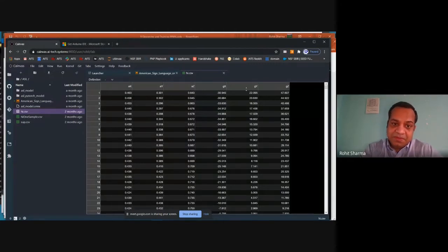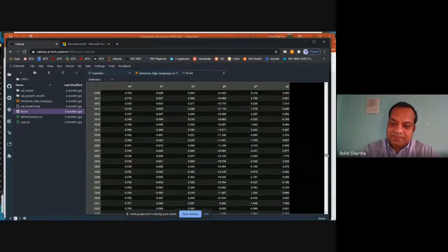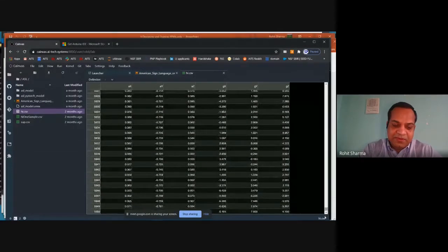There are 6 columns: AX, AY, AZ for acceleration, and GX, GY, and GZ for gyroscope. And that's how we collected this data set with over 6,000 samples. And so that's how you would collect the samples for every sign you make.